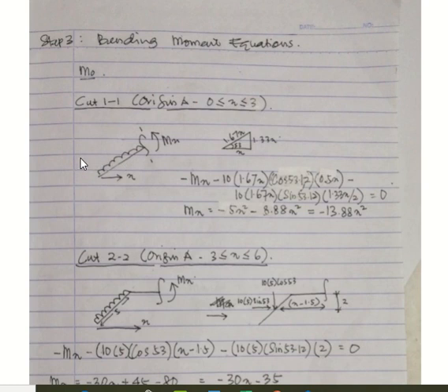For the force in the x direction, you must multiply with this dimension. This dimension equals 1.33x divided by 2, because the load is applied at the midspan here, equal to 0.667x. Then you resolve this equation to your bending moment equation now.